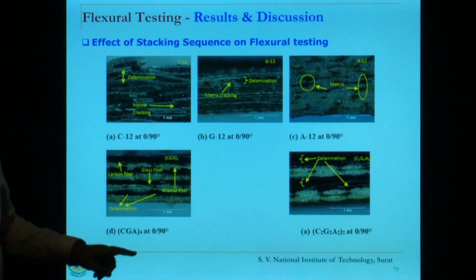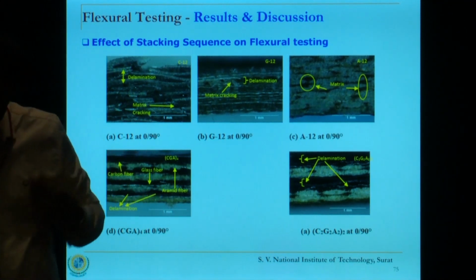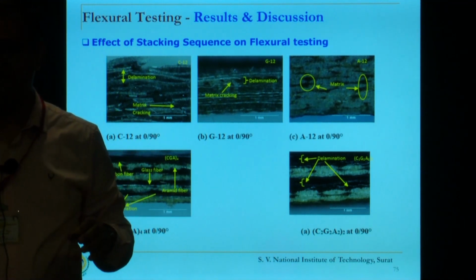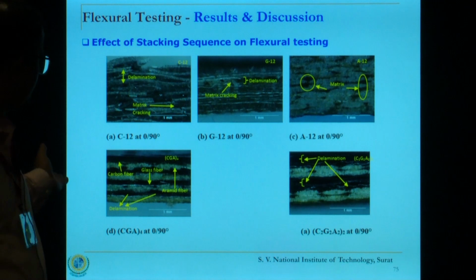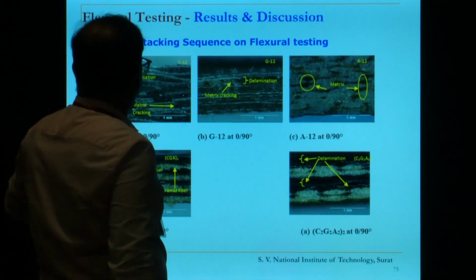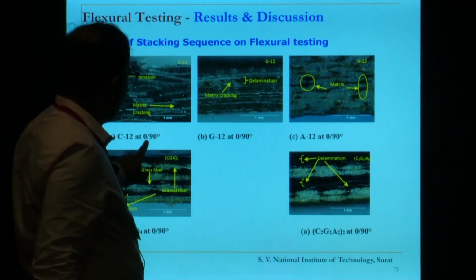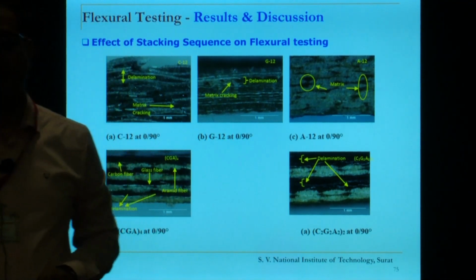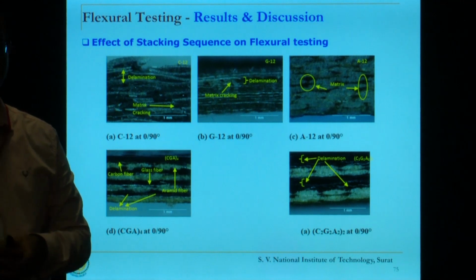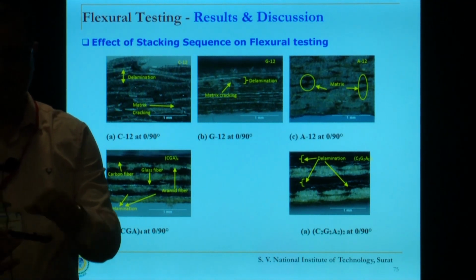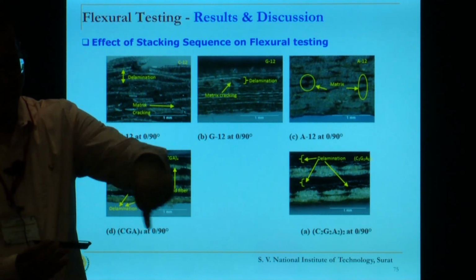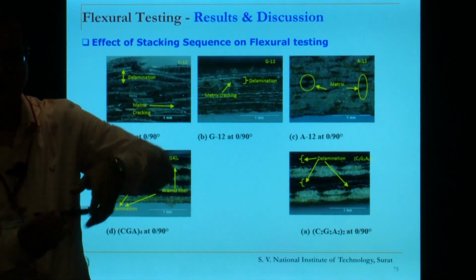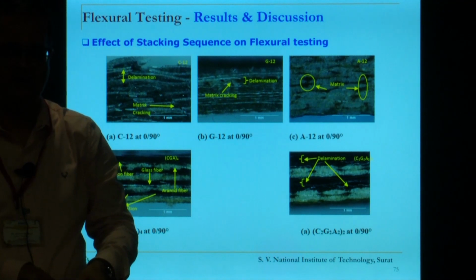Individually, if you see the glass fibers, they would easily get delaminated, their strength would be very low in that case, and naturally the result is also similar. Now, this is a situation where we have placed the fiber orientation in 0/90. What is 0/90? If this is the part for flexural testing, the fibers are laid along this part and at 90 degrees. This is that situation.